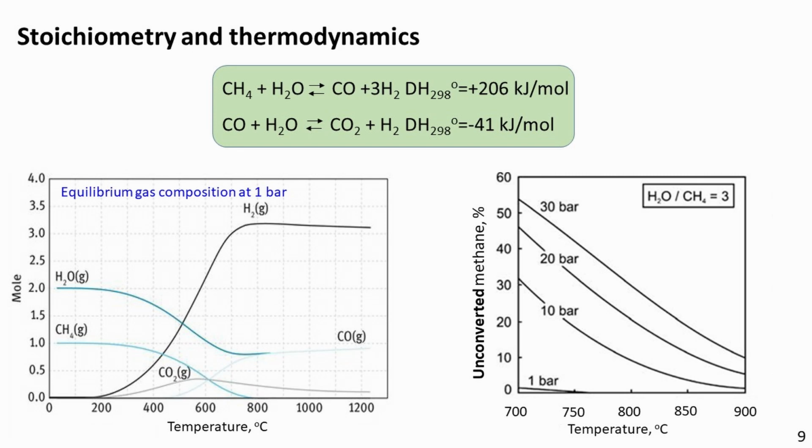From the thermodynamic viewpoint, steam reforming does not require high pressures. Generation of syngas is done, however, at high pressures, since downstream applications of syngas in methanol and ammonia synthesis require high pressures. Also, high pressure is unfavorable for equilibrium and thus requires high temperature and excess steam. Expensive compression of syngas is avoided. In practice, the increase in temperature is limited by the thermal and mechanical stability of the tubes.